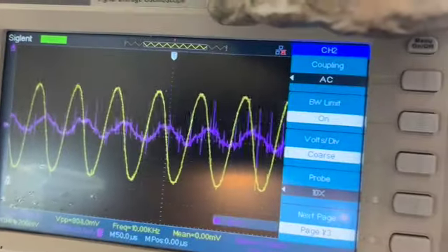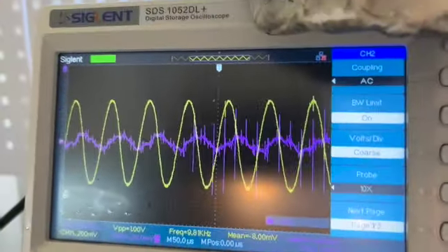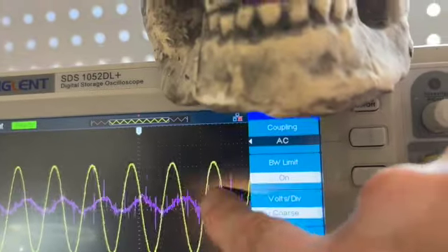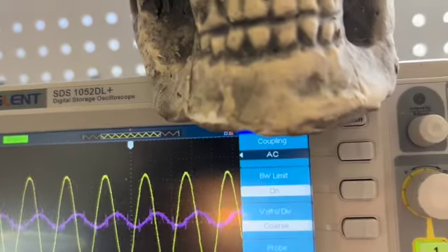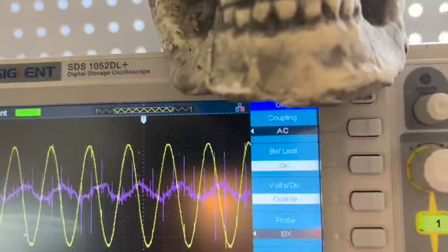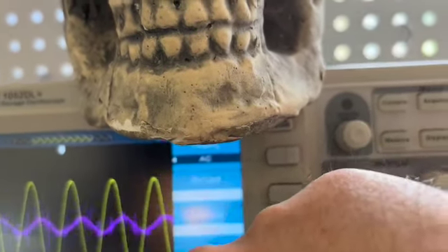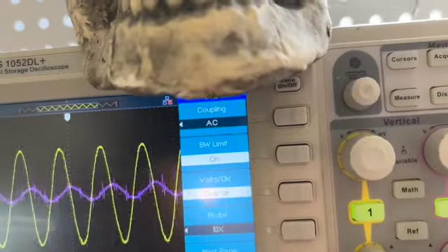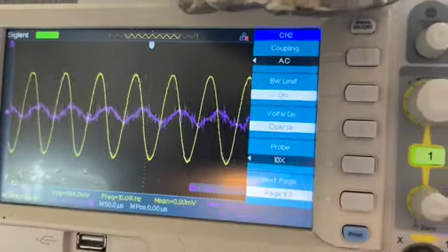Okay, folks, so this is our output at a really high frequency of 10 kilohertz. The yellow line is our input. As you can see, it's got a pretty nice, good size swing on it, but our inductor here has barely got anything going through it. As a matter of fact, our signals are scaled down. So this is 200 millivolts per division for our input. Division is the distance between this line and this line here. And our output here is at our lowest possible setting, 20 millivolts per division. So again, same unit for division, but it's only 1/10 as much. And of course, this is because of the reactance.